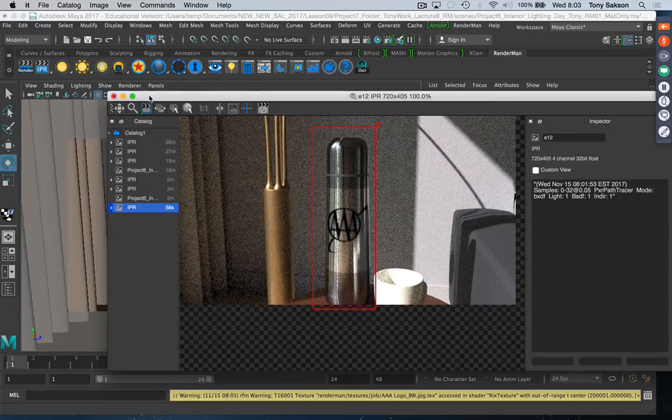It simply means that you've got a material, wherever you don't have a logo, you need to have some coverage for that. Anybody here during modeling ever have your model mesh turned or the shaded mode turned green on you? Okay, if it turns green, that means it lost its material property. We don't want that to happen, so Maya, by default, puts into every file node something called a default color. And it gives it 50% gray, just like everything else.